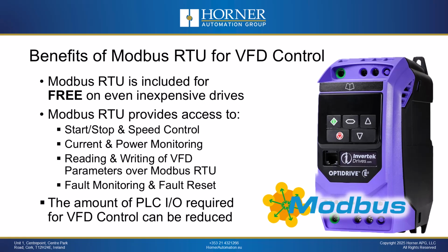Modbus RTU allows you to read faults as well as reset faults. Using any of these functions over Modbus will also reduce the amount of PLC I/O that you need to allocate to the drive. You can choose to have some functions of drive control done using hard wiring from your PLC or your Horner OCS, and also some functions done over Modbus. So there are a lot of benefits to using this free built-in protocol.